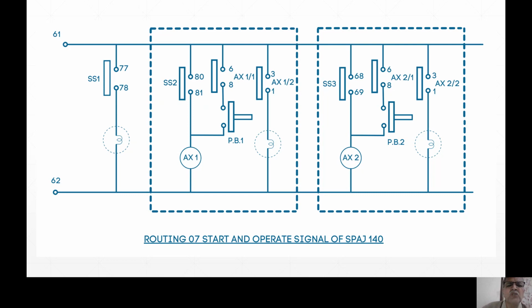Current coil is there, voltage coil is there. Current is not passing through the current coil. I am not using any power, but voltage is obviously there. So because of the voltage, the disc keeps on moving very slowly, however, but it keeps on moving. And because it keeps on moving, it registers. And because it registers, the registering mechanism will show money. So the meter reader will come and charge money.